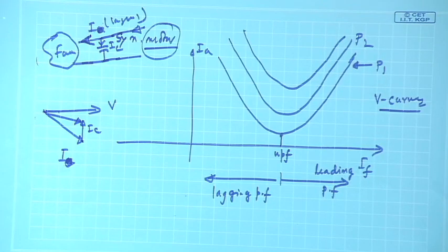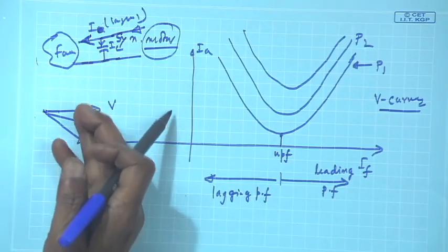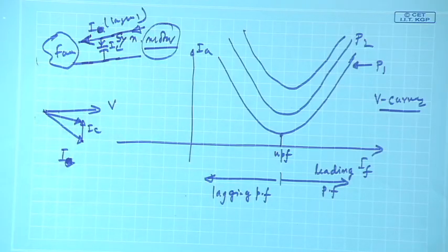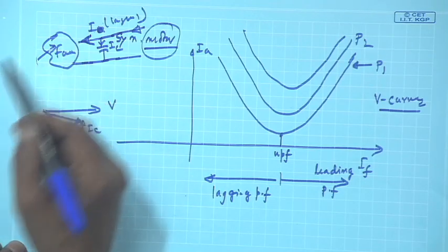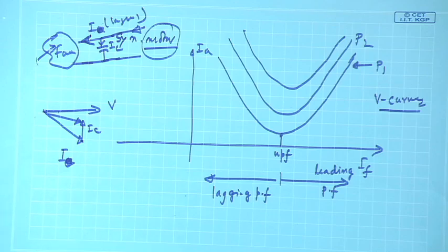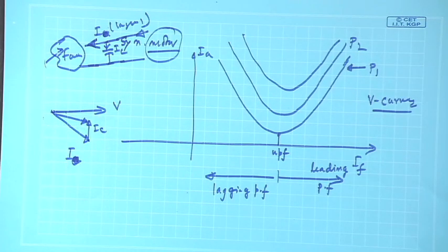So, earlier people used to connect capacitors, but in fact, you can choose your capacitor such that it may operate at unity power factor as well. But the point here is, if the load changes in this factory, the capacitance needed to attain a certain power factor will also change. You have to connect another capacitor, things like that.